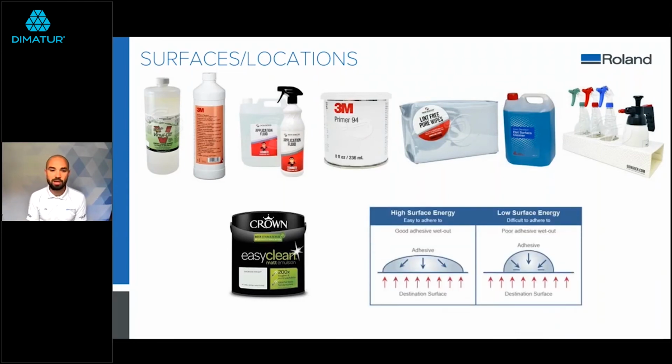Another thing to be aware of is high energy and low energy surfaces. Low energy surfaces, again, will repel adhesives. So you want to just check what the surface of the wall or material is that you're going to be sticking onto. It might be that it's not a painted wall, that it's a wood interior wall, or maybe a plastic partition or something like that. Things like HDPE are low surface energy materials, so they will require a different adhesive from your materials.